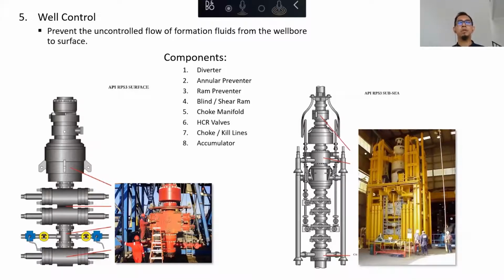So once you have a drill pipe, say I want to drill the whole section with 5-inch drill pipe, before you start running the whole BHA, the pipe ram face needs to be set or replaced to the 5-inch type. If you drill with 4-inch or 4.5-inch, then you need to remove the 5-inch piece and install the 4.5-inch. So this is the kind of preparation that we need to do and be aware of.